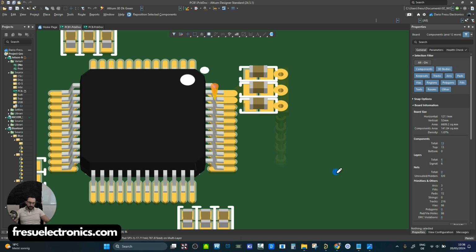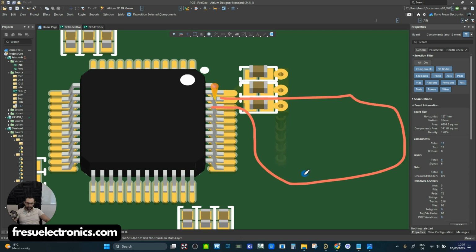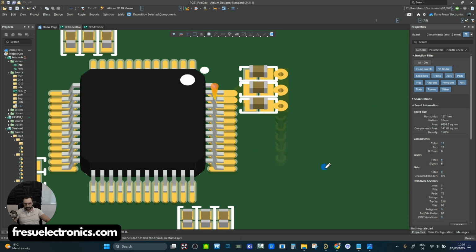Then the other problem that we have with the radiated emission is that once we have this transient current flowing through these loops, then we also have a certain impedance connected in the return reference plane. So when we're thinking about the current, we have to think also about where the current is flowing through. And in the return reference plane, the larger this loop becomes, the larger the voltage drop is going to be. And this means that this voltage drop can couple to other cables and to other traces, and then this voltage drop will cause the radiation.